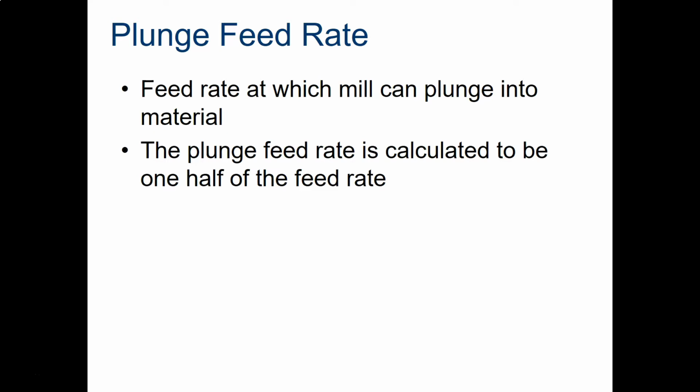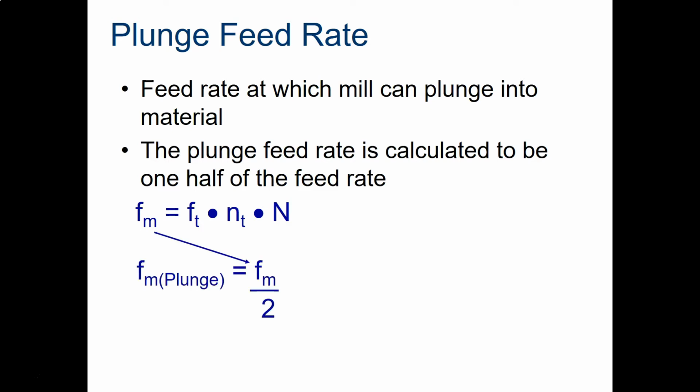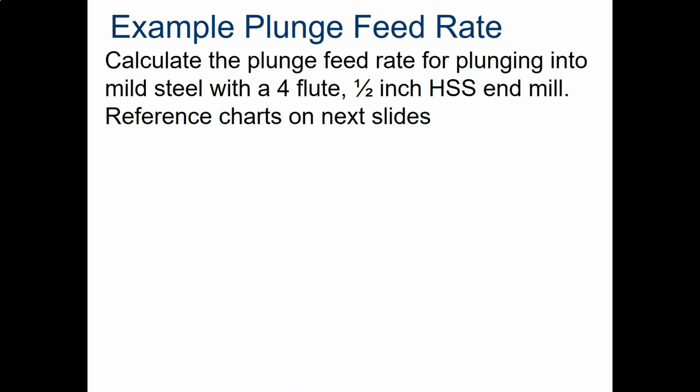We could be dealing with, say, a plunge feed rate. Plunge feed rates, driving down into the material from above, use the same formula. You just go half as fast, so you divide by 2. Take a moment to record this if you need to. Let's use a plunge feed rate in an example.